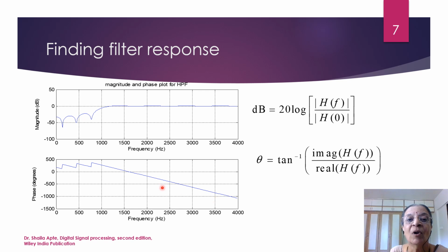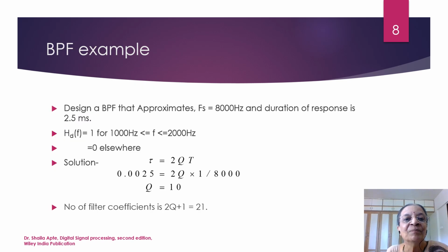So this is what is required for performing the filtering for the speech signal. For speech signals, linear phase is essential. When linear phase is there, the group delay for every particular frequency will be constant, and all frequencies will be delayed by the same amount, thereby causing no phase distortion. So this is the essential characteristic for speech signals for filtering.